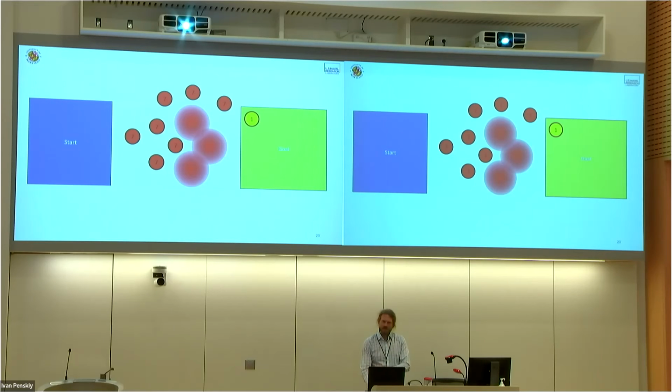The way this works is based on a very simple queuing idea. The first robot in the goal says, hey, I'm in the goal, I'm number one. If you are some robot and you can hear number one, then you become number two, and so on. The robot that hears the lowest number becomes the next number. And if you have a couple of robots equally distant from the goal in number of communication hops, then the robots are going to link to the robot that has the lowest distance. So the 7 here is linked to the closest 6 robot.